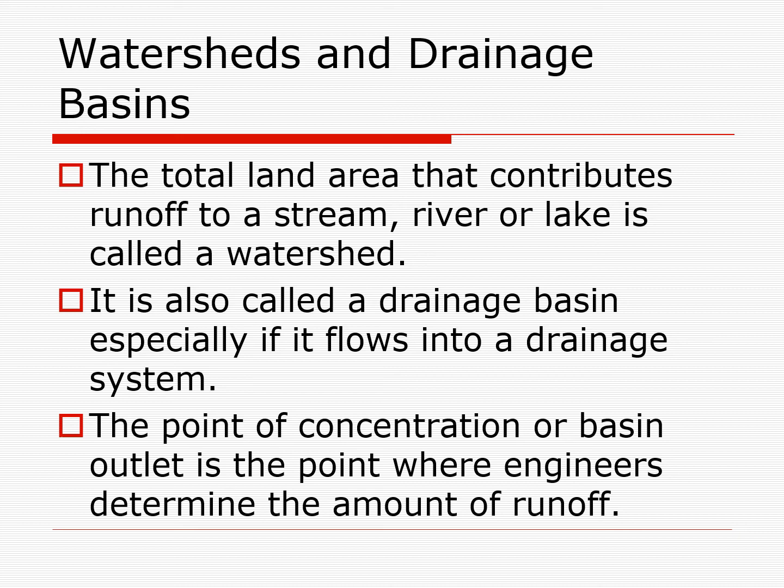One of the ways that we've helped to control some of the flooding has been with regulations that require that the amount of runoff after development on a property is the same or less than the amount of runoff prior to development.